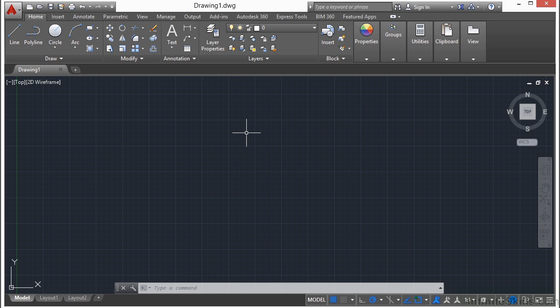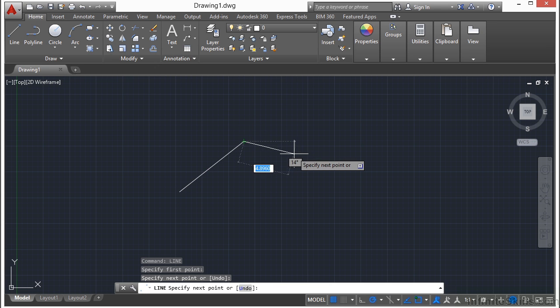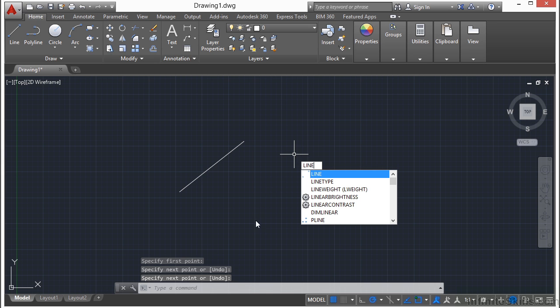Now, another way to execute commands in AutoCAD is through what's called the command line. It's found here at the bottom of the screen. That's this guy right here. You can directly input commands right into it by typing them on the command line. So you can click inside here and then start typing in a command like the line command. Press enter, and now I can draw lines. Also, I can just start typing. I don't necessarily have to put it down in here.